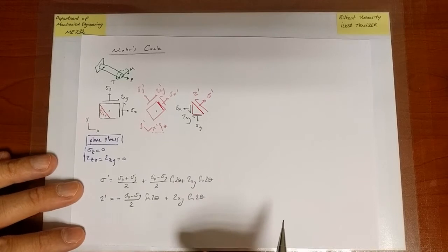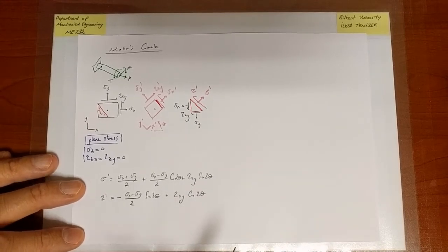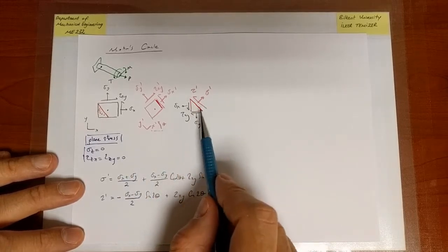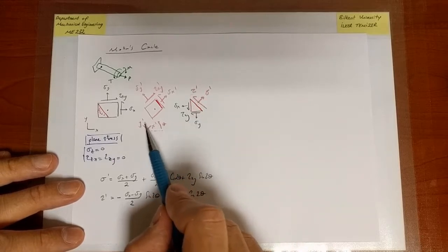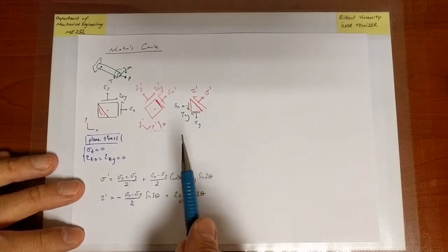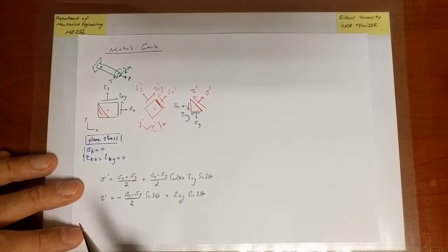Could be associated with an anisotropic material, isotropic material, elastic, thermoelastic, whatever, right? So you give me a state of stress and I can tell you how its components look, how the normal and shear stresses look, what their values are on other planes, right? On a different geometric picture, okay? And that is based on equilibrium alone. That's why it applies to any kind of material behavior.